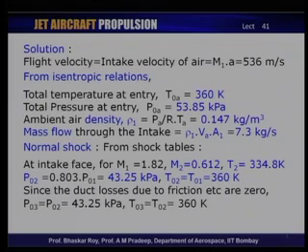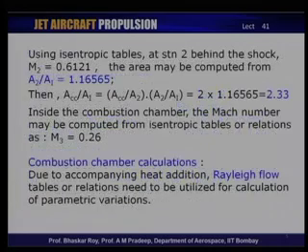Now, it is prescribed that the duct losses are to be completely ignored. So, there are no losses there, and as a result of which P03 at the entry to the combustion zone would be equal to P02, and that would remain as 43.25 kilopascals. Temperature of course continues to remain the same, since no work has been done and there is no heat transaction either. Hence, the temperature remains the same as 360 K.